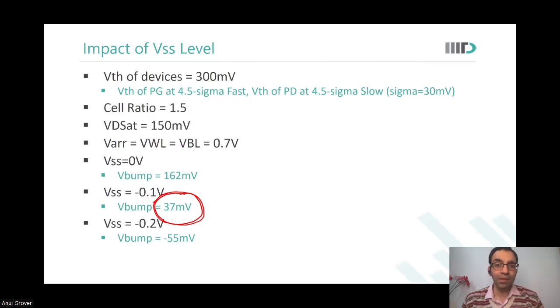Yes, sir. You only do this in the read cycle, only in that limited part where you are doing the read operation. Everywhere else, everything is 0.7. Only where you're doing read operation, there you have done this voltage boost or negative VSS, and you recover the performance, you recover the functionality. Everywhere else, it is lower power. That is when you will gain some benefit. That is why it is called an assist scheme. Okay? Yes, sir. Thank you.